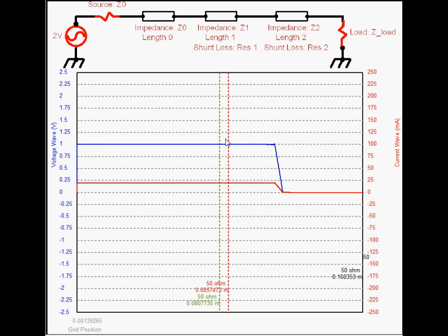And then the next obvious question is, what is that source impedance? What does that mean? Well, the impedance of the transmission line could be like a coax line. And that coax line, if you were to put a multimeter probe on it, you're going to see that it's an open from a DC perspective. However, there's a relationship when that voltage wave is traveling down the line. There's a relationship between the voltage of the line and the current that's going down it.